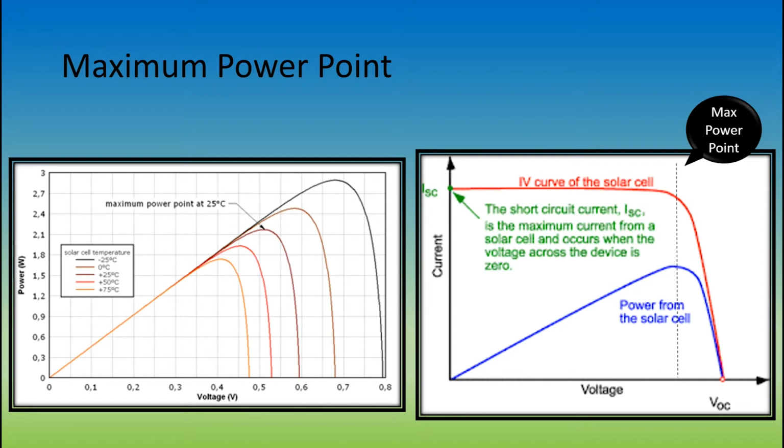Voltage, however, depends on the load resistance and temperature. The load resistance is essentially the total resistance of the components in the connected circuit. In order to generate the most power, a solar panel should be at low temperatures, in direct sunlight, and should have an appropriate load resistance.